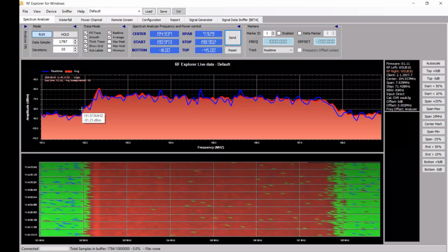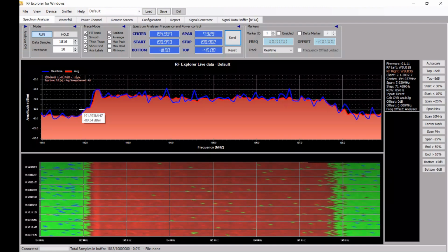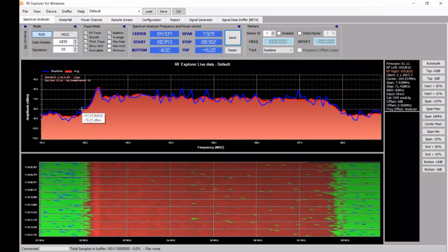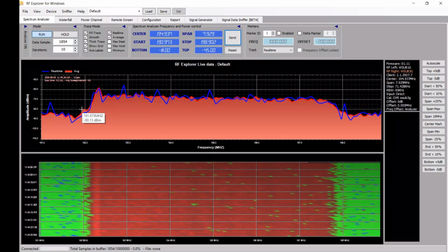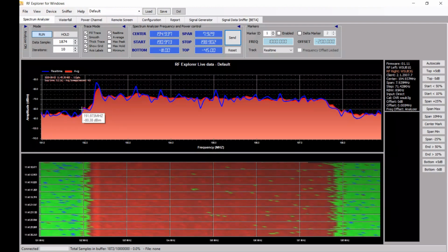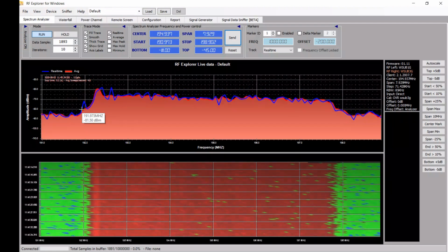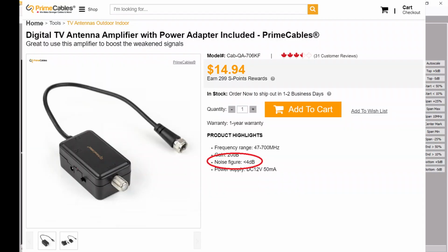And why is that? Well, it does make sense, because what amplifiers do is amplify. They amplify everything. But what they also contribute to this whole equation is they introduce noise. No amplifier has no noise. Okay? It produces noise as well. And most amplifiers of these sorts specify around 2, 3, 4 dB of noise.